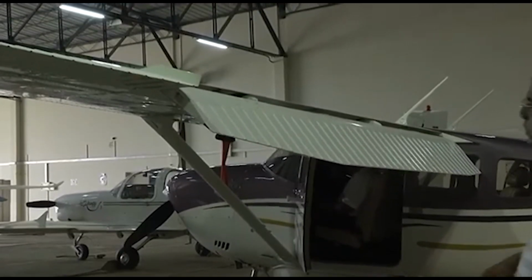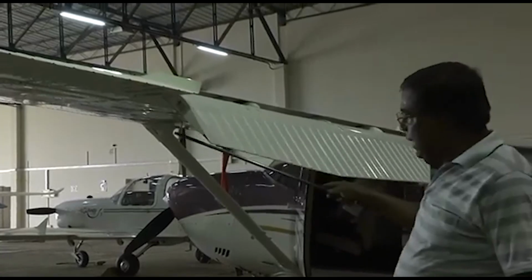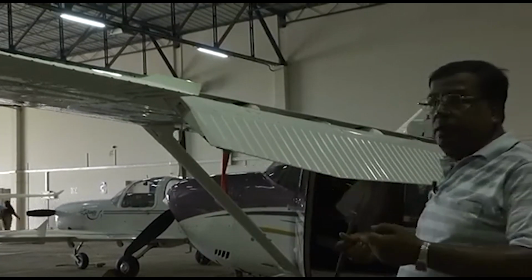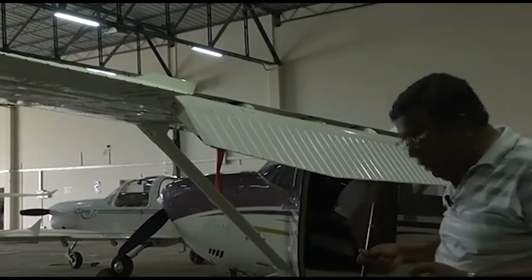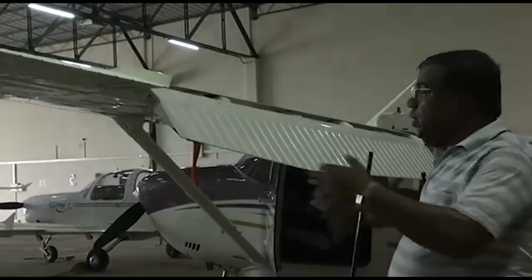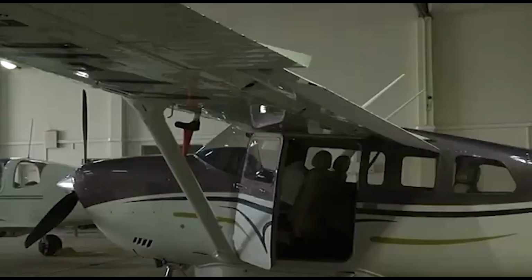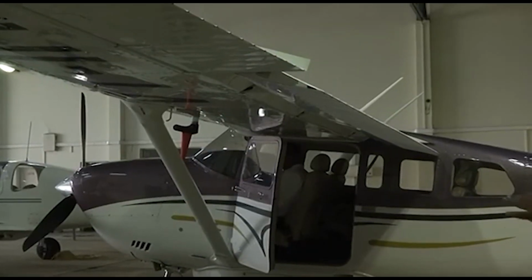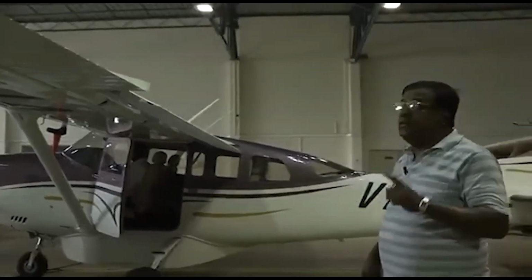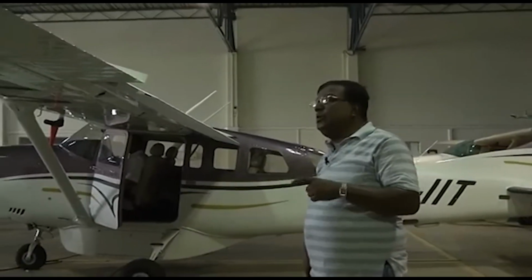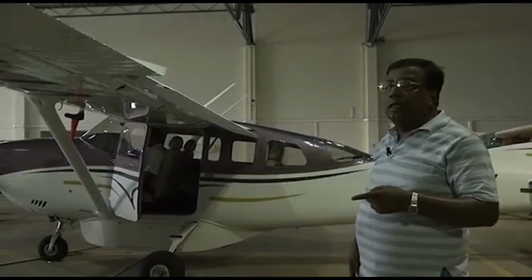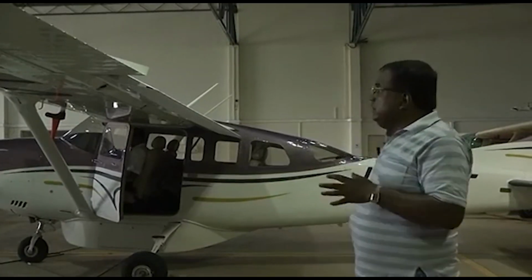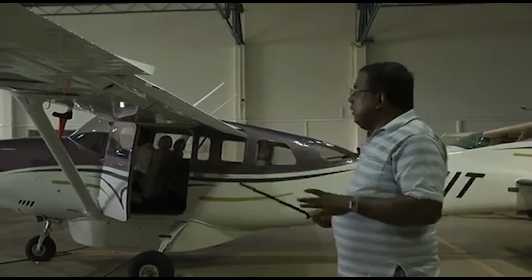And it's very evident now, you see, during landing when you are putting 40 degrees, primarily we are trying to increase the drag. That helps in braking the airplane to a shorter distance, because this is also important that we need to have a shorter touchdown distance, right? Please understand, when I say by putting the flaps down we are increasing the lift, but that is at the cost of drag. So that is why in takeoff, we have to put a lot of throttle, almost power on. And the CL by CD max reduces, right? Okay? So this is the primary function of a flap.